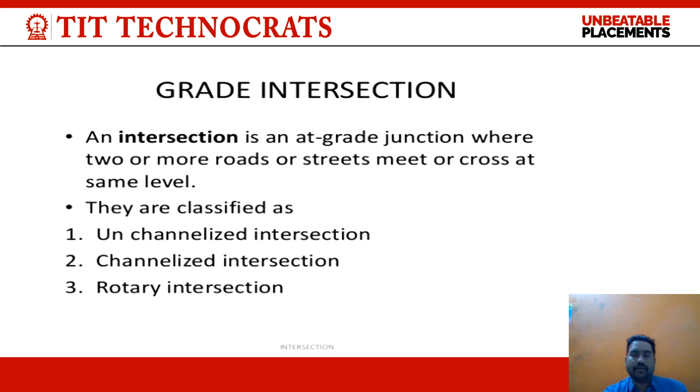Now we are discussing the next, which is grade intersection at the same level. What do you mean by grade intersection? An at-grade intersection is a junction where two or more roads or streets meet or cross at the same level. In a grade separator, there are different levels, but in an at-grade intersection, they are at the same level. They are classified as unchannelized intersection, channelized intersection, and rotary intersection.